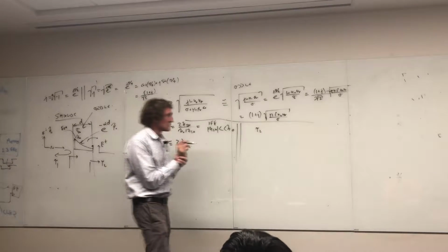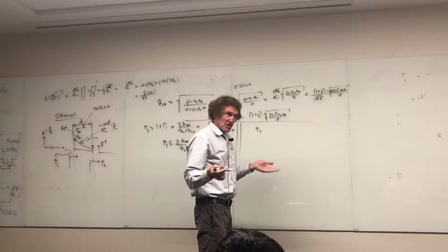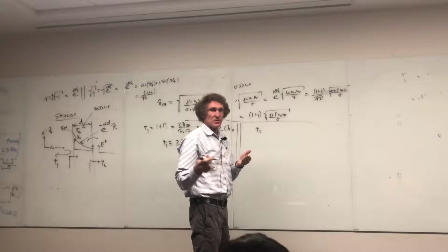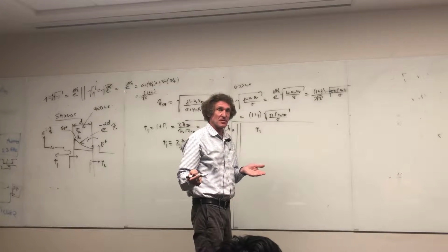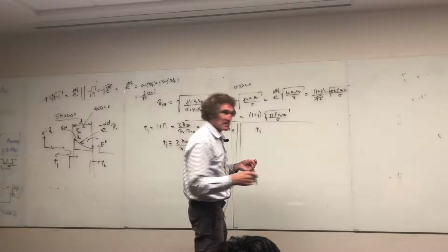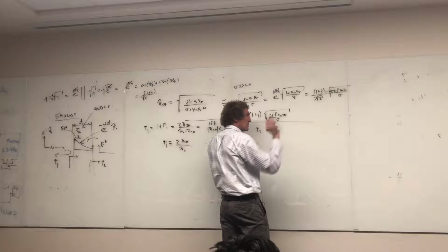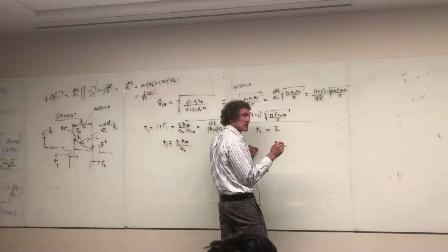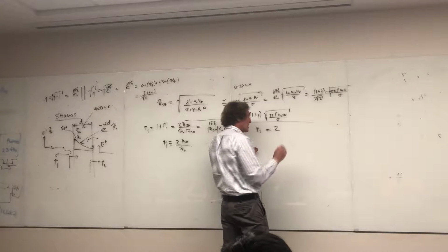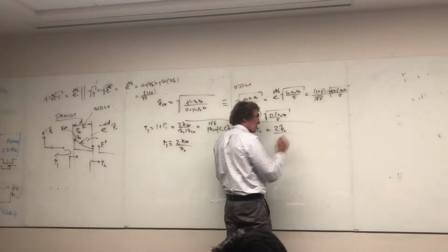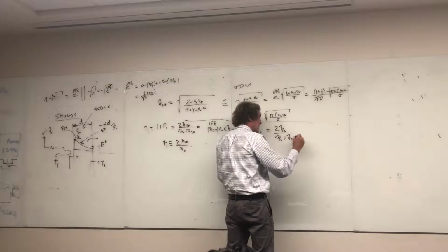That's the basic thing, because that's what you're going to be doing, designing stuff, not analyzing it. In the real world, generally, most of your work is design. It's not analysis, unless they've created something and there's a problem. Then you've got to analyze what's wrong. So tau 2 is going to be twice the impedance you're going into. What's that impedance? If we're in the shield and we're going out of the shield, what's the impedance we're going into? Leave it as eta naught for now, right? Over eta naught plus eta shield, right?